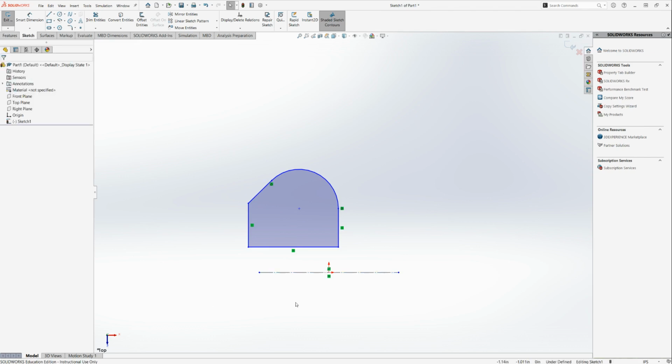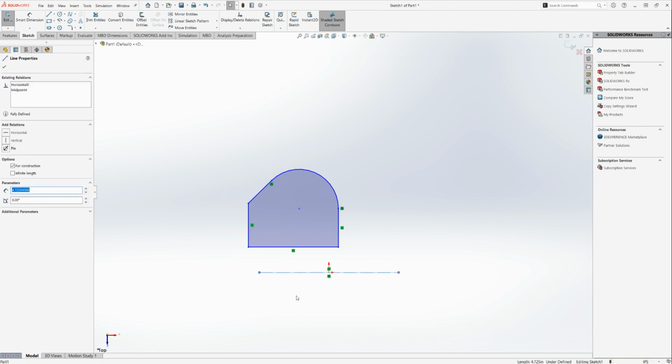And by selecting this line, that's already fixed to the origin, I can look up the existing relations, and this will tell me it's got a horizontal relation and it also has a midpoint relation. It gives them a number based on when you actually clicked it and when you confirmed its new relation. So I can go up here, midpoint 4, and click delete. That'll also get rid of it. I'm going to undo really quick with Control Z.